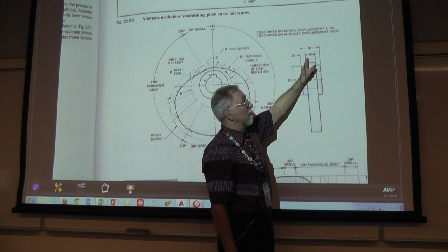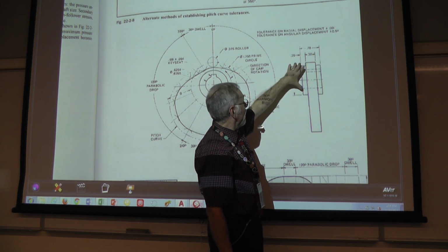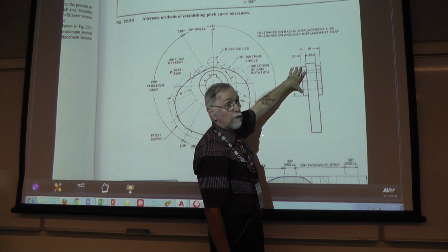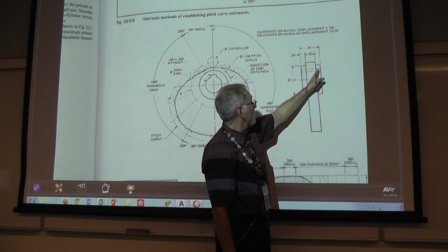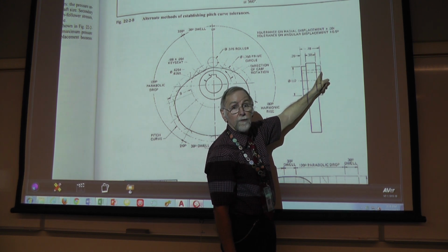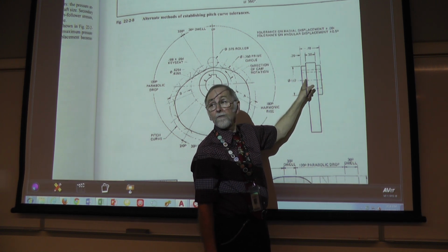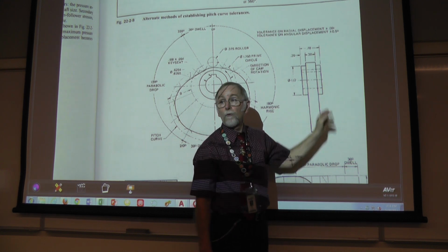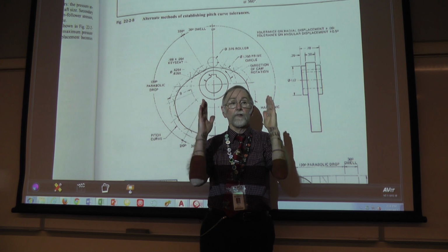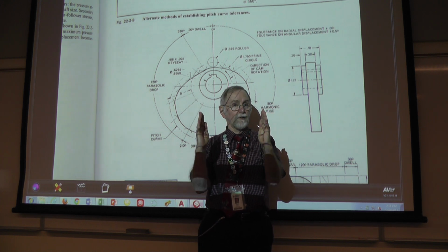This particular plate thickness is 3/8 of an inch. Ours is 1/2 inch. The hub diameter is 1 3/4 inches, and it's 1.5 inches long. If the plate is 1/2 inch, the hub is going to protrude out from the back of the face of the cam by 1/2 inch, and it's going to protrude out at the front by 1/2 inch. 1/2 inch, 1/2 inch, 1/2 inch equals 1.5 inches. So it is centered off of the plate itself.